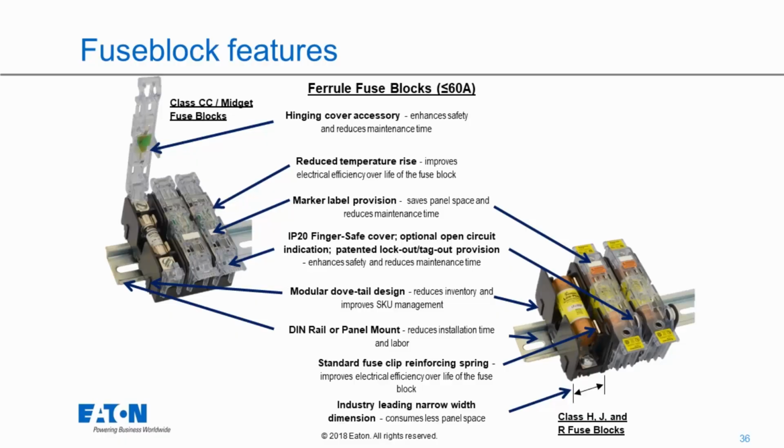And then we have a standard fuse clip reinforcing spring. The nice thing is we're going to make sure when you put a fuse in, you want it to be a nice tight connection in your system. If you've got a fuse and it goes in too easy or it's very loose, you certainly want to inspect your system to make sure it's operating properly and protect your system. Make sure it's a nice tight fit when you go to put that fuse in. It should not be loose.